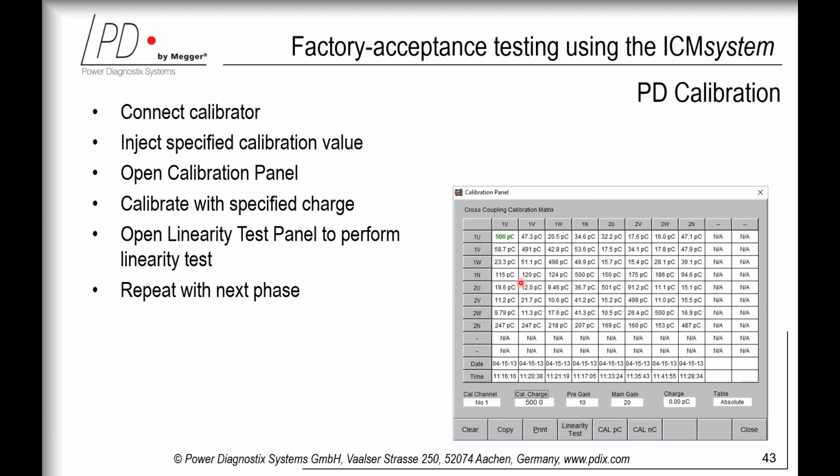Especially as shown here, it's worth to mention that depending on the transformer type, the neutral shows a rather strong cross-coupling. So despite the fact that it does not have to be tested if you have already the 6 bushings, here you would have them as 1U to 1V and 2U to 2W, sorry, not V. It still can provide valuable information later on. Considering the structure of a transformer, this is also logical that the cross-coupling is rather strong. The bushing with the test tap is on one end of the winding, and the neutral or the start point is the other end of the winding.